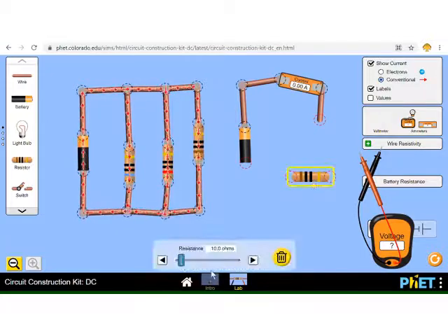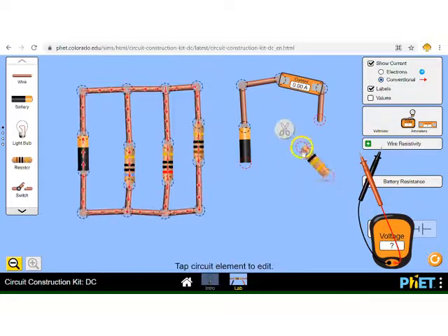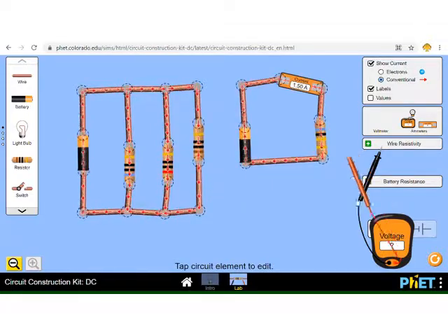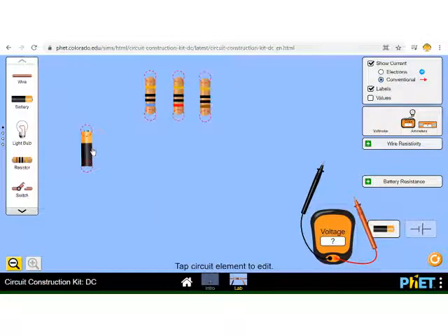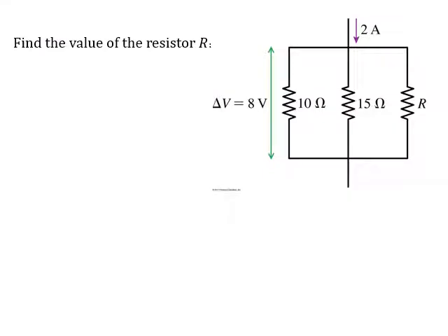So there's a resistor. I'll click on it, set the resistance at 6 ohms, and then I'll put that in my circuit. And I have to connect it to the battery with a wire. So we see that we get that net current flow of 1.5 amps, same as put out by the battery in the previous part. And you get the same potential of 9 volts. So these PhET simulations can be really nice just to help you verify that you got the right answers when you did your problem. Let's do another quick example, but just a slightly different twist on it.